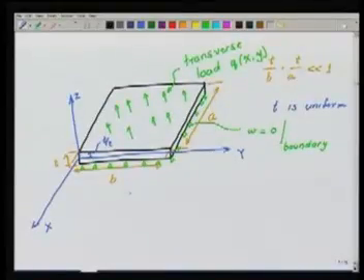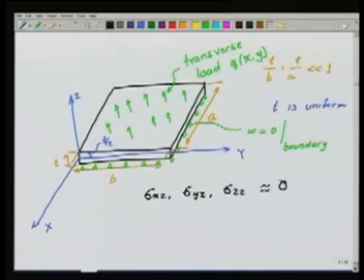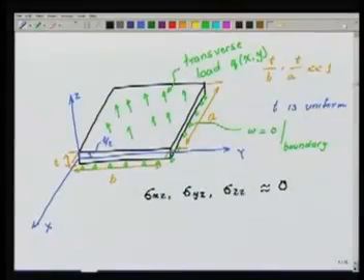There is a standard way, what we call the St. Venant semi-inverse method, or in the strength of materials way, where you try to figure out what the deformation pattern is going to be. So here for this plate, it can be shown when it is thin that sigma xz, sigma yz, sigma zz are essentially 0. That is, they can be neglected with respect to sigma xx, sigma yy and sigma xy. That is, the magnitude is much smaller as compared to those.